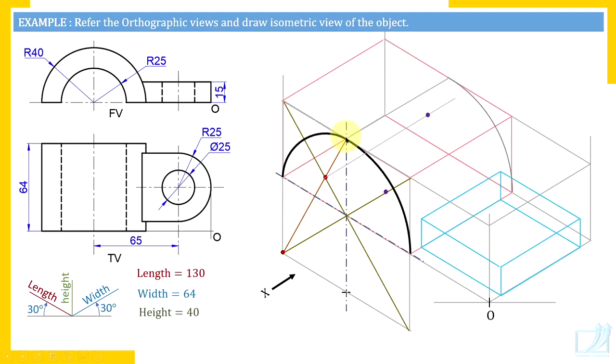Similarly here also we have already transferred this highest point here. So from corner of this backside surface to the highest point you are going to draw that arc. So use the same radius, that is radius of this smaller arc, take it in compass, and from this shifted center draw that. So this is how we have completed the semicircular end on the back side.